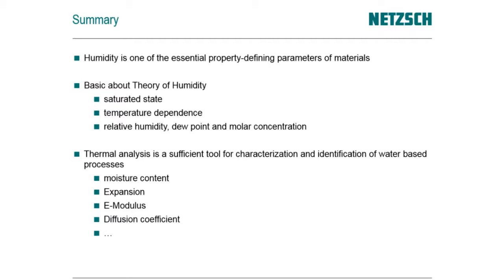So I have hopefully explained that we have a saturated state which is defined by evaporation and condensation processes, that this state and therefore also the amount of water inside of a certain volume is highly temperature dependent, and that this whole thing can be explained or characterized by the terms relative humidity, dew point, and molar concentration.